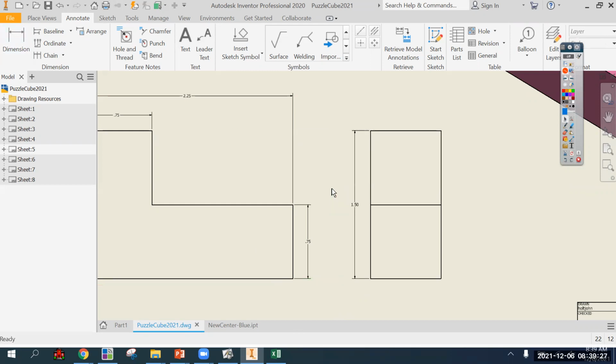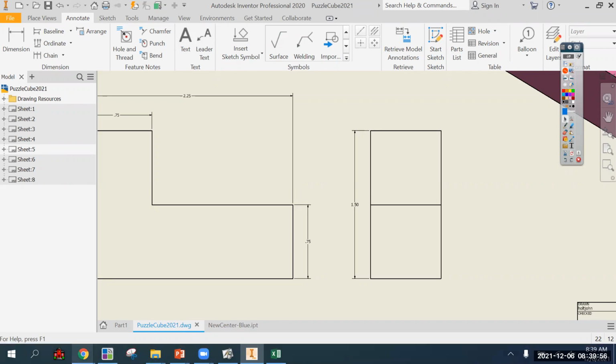And so these parts for the Puzzle Cube, I keep saying because it's true, are very simple. So the trade-offs are going to be very obvious as to whether it's better to put the dimension here versus over there. When we get to more complex things, you are going to have to run down our hierarchy of issues.